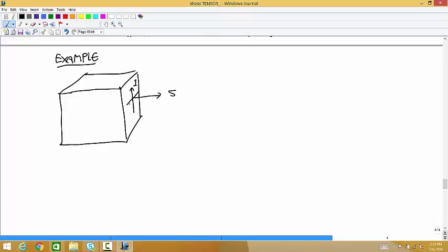The XZ stress is positive 2. And then we get matching ones for each of those. On the Y face, we have a Z component of the traction of negative 10, so that's 10 going back towards the back. And that means we have to have, on the front face, 10 down towards the bottom. And then the last thing is, on the Z face, we have a normal stress of positive 3.